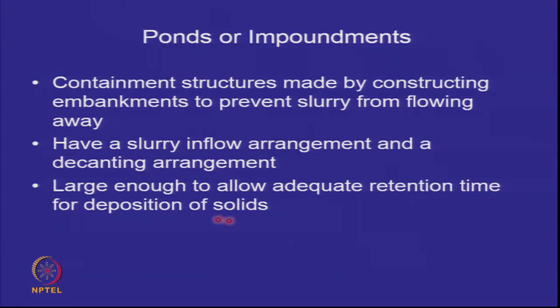These ponds have to be large enough to allow adequate retention time for deposition of solids. So the design of these ponds, the size of these ponds, depends on, do you have adequate time for the fine particles to settle down when you take away the liquid from the top. If you don't have adequate time, the fine particles will come out with the supernatant liquid. I showed you that sometimes you see very milky kind of or muddy kind of water coming out of the decanting structure, which is not desirable.